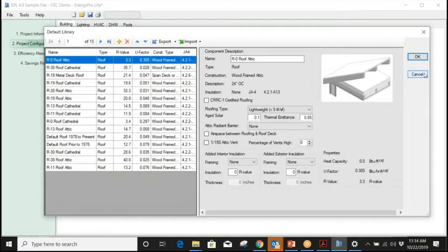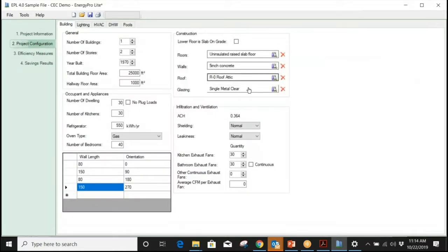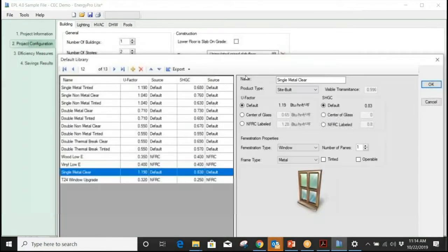I think it's been pretty clear from the last two examples, but you would just hit the plus sign and import the roof and do like a 4-inch or a 6-inch roof. A lot of concrete buildings have exterior added foam insulation. So if it does have that, just enter the R value of it here, and that will calculate for you. Great, thanks. All right, for glazing.